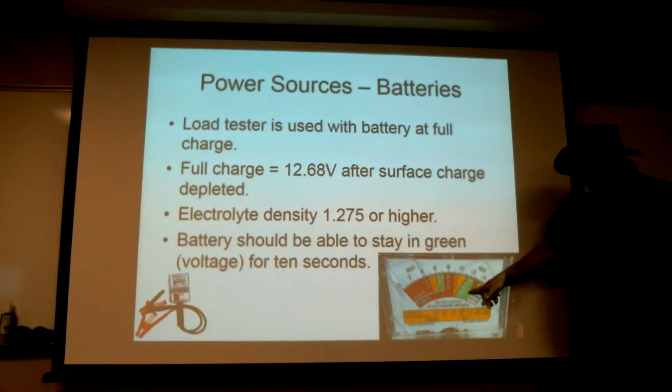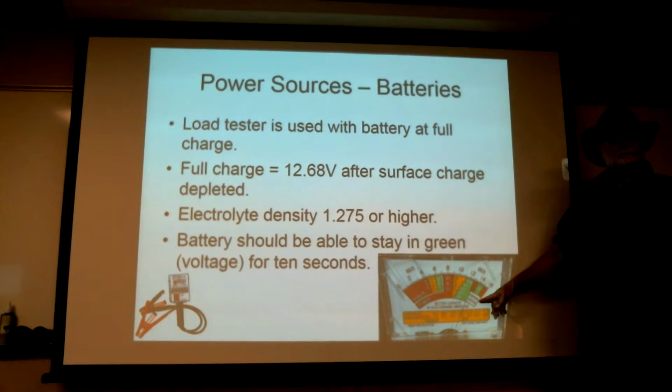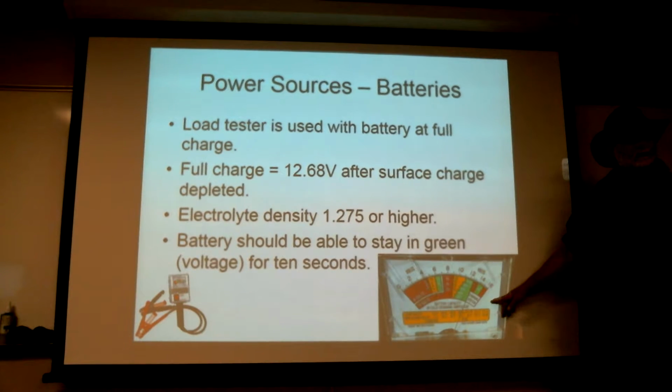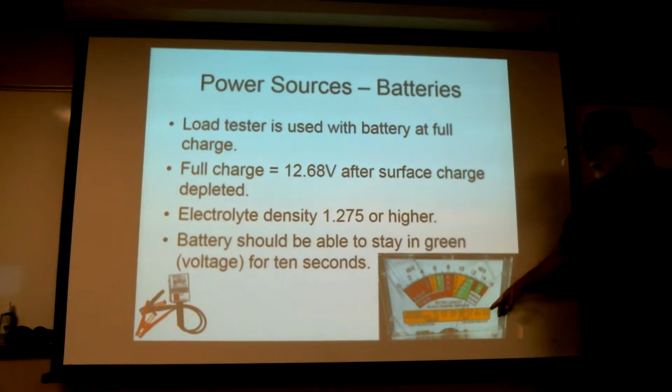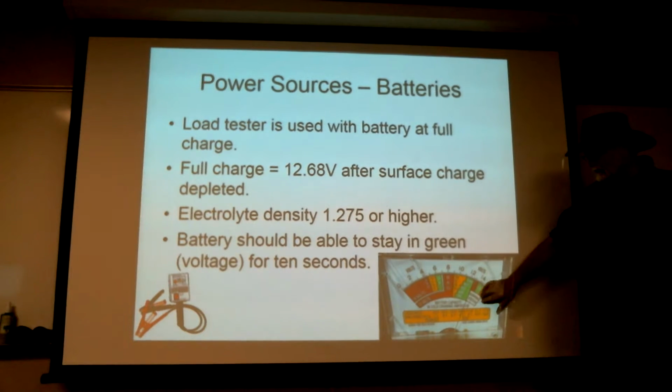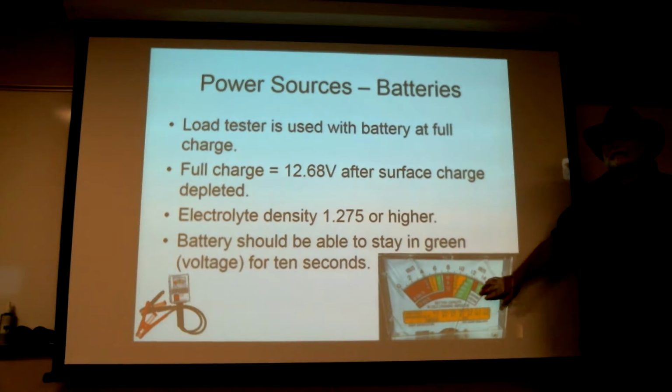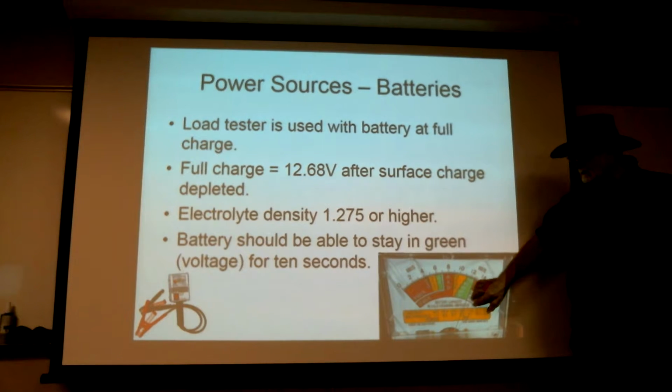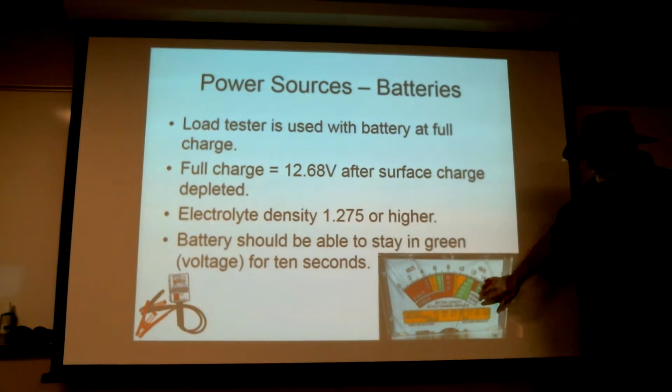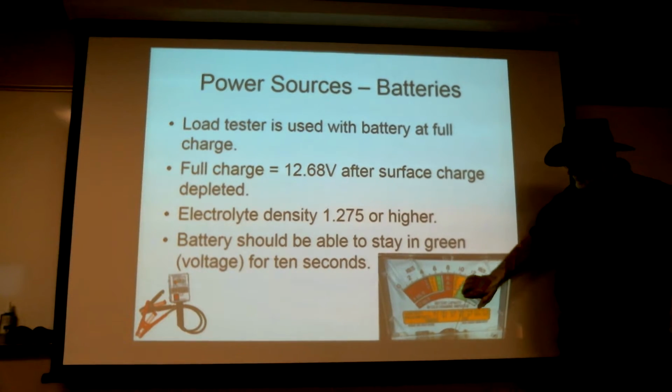And this is showing the charging system. The battery can't go higher than this, so the charging system will have to. So I put it on there, start the engine, and if the charging system voltage is up this way, then I know the charging system's working. That's a handy feature. All this is a voltmeter, though.